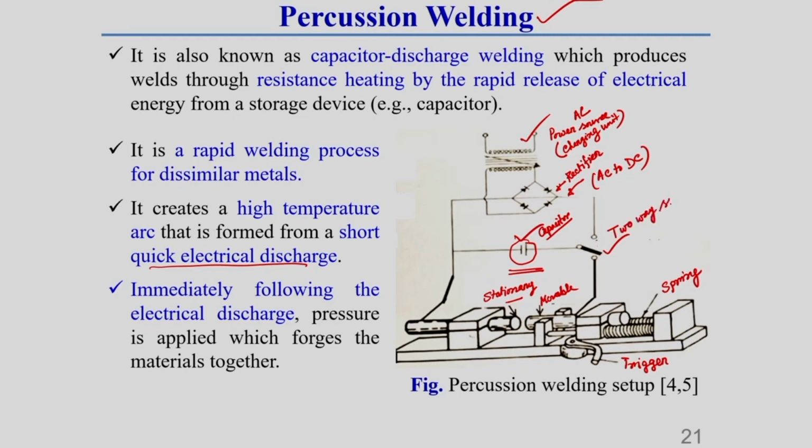Once it is connected to the upper connector, it will start charging. Once it is connected to the lower connector, it releases this stored electrostatic energy, so that due to this sudden electrostatic energy from the capacitor, a sudden arc and sudden welding phenomenon occurs. That is why this is called the percussion welding process. This you should keep in mind.